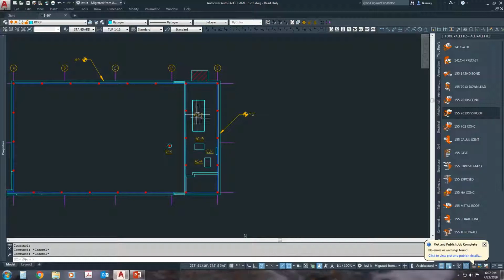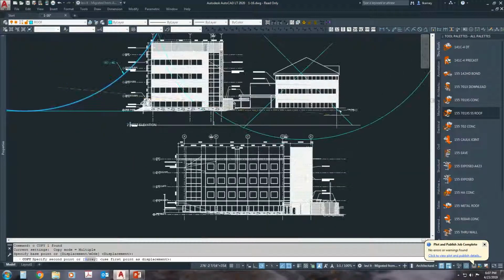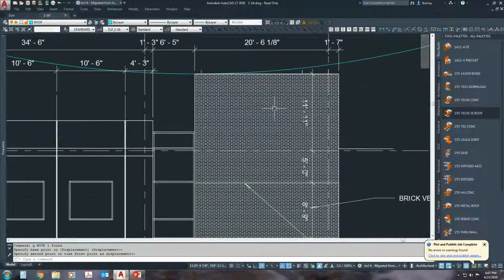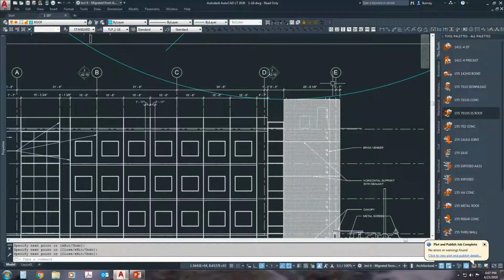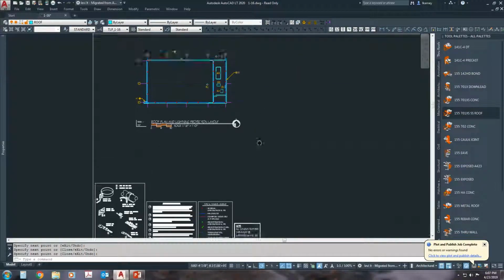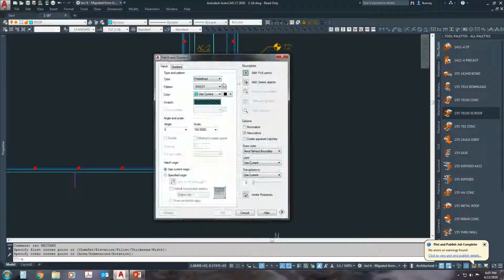So keep in mind, these mechanical units are also located down in a pit. The elevation doesn't clearly show it, so I'm going to draw them in here, but that's approximately where they're located. So since we have lightning rods on parapet for parapet, essentially everything in that pit where those units are located is also in the zone of protection, which means those air conditioning units and condensing units do not require any further protection.